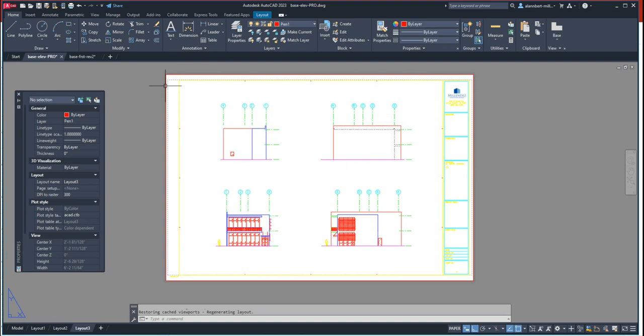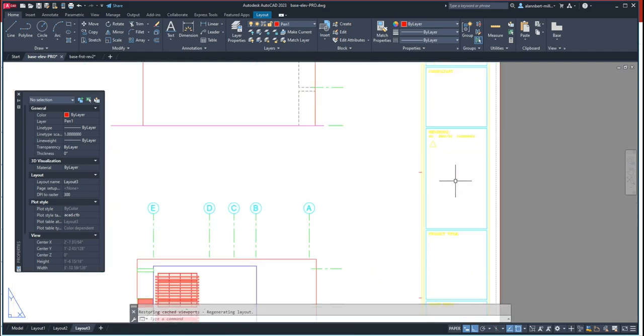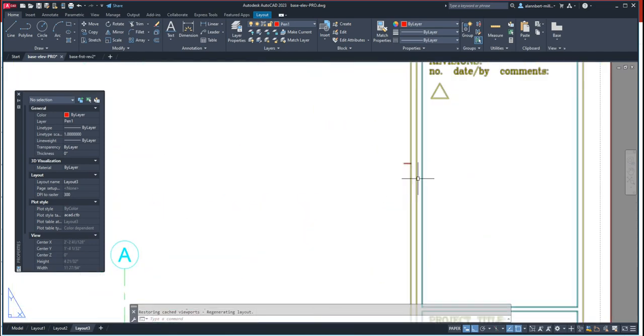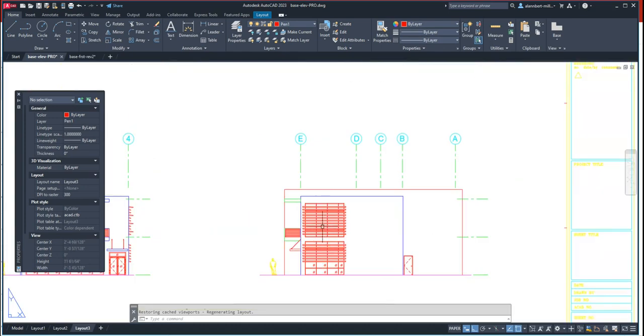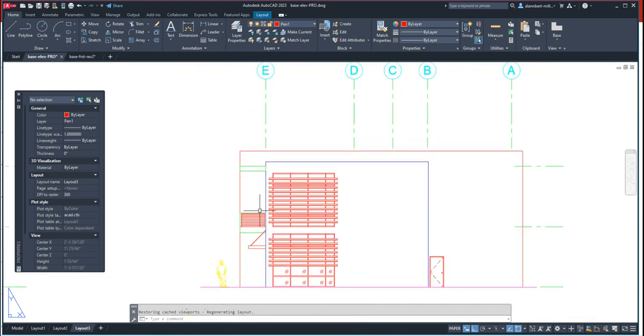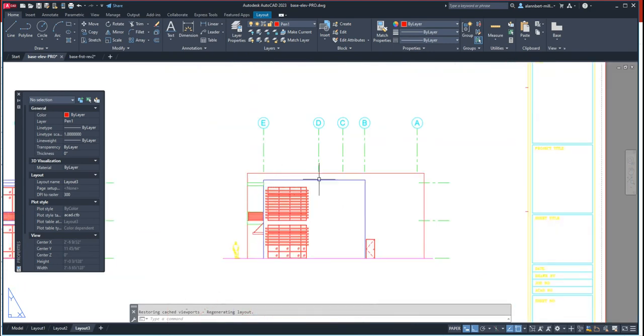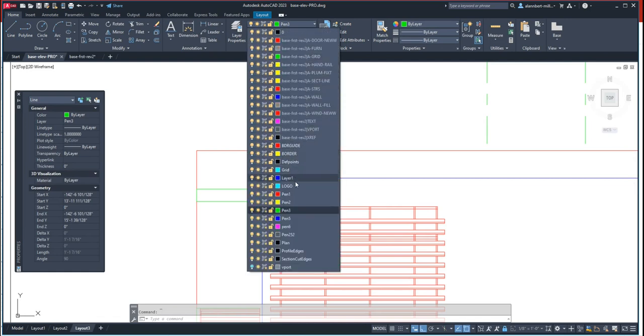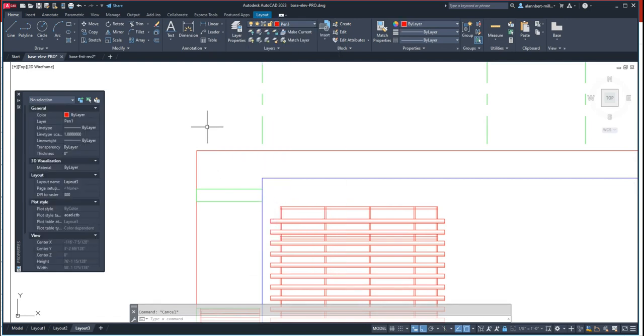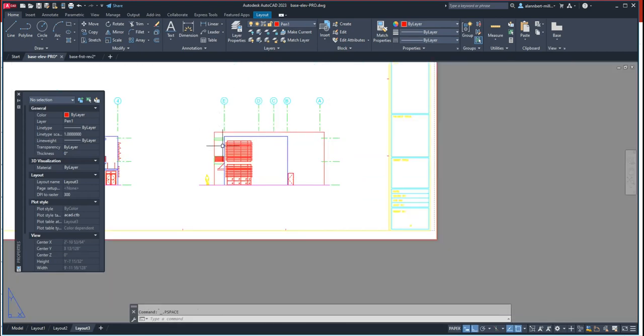Working on a white background with colored lines, especially green, yellow, and cyan, is sometimes really hard on the eyes. But working with colors, our brain tells us that red is the thinnest. So anytime I see red, that means it's the thinnest, and every time I see a blue or a cyan, it'll be thicker. I've just noticed something here, this one is supposed to be blue. So I'm going to double click, change that to pen 5. There you go. And then simply zoom out.